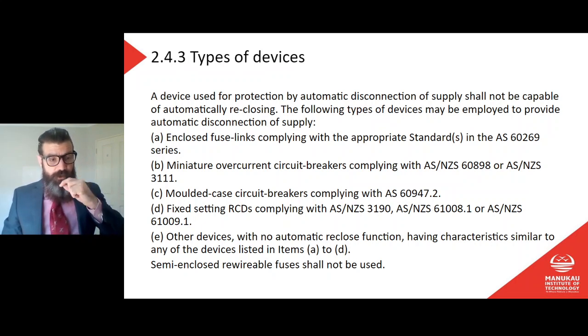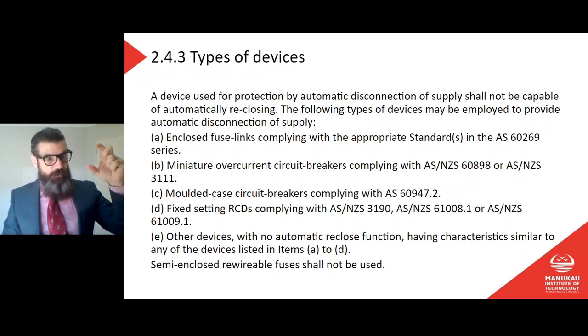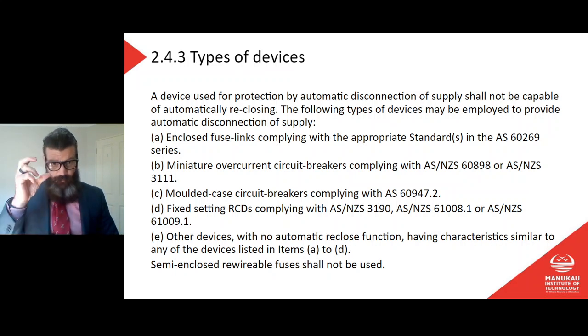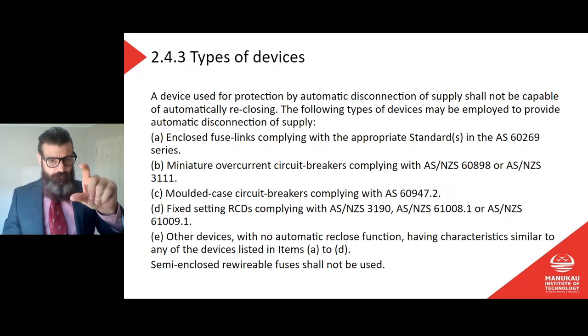Plug-in circuit breaker. So this is something that will, in the rewirable fuse base, you just take out the fuse holder, throw it away, you get a plug-in circuit breaker and you plug it into the fuse base, and it acts like any other normal fuse circuit breaker. It's a great option to replace a rewirable because it doesn't require you to replace the base at all. It doesn't require you to disconnect any wiring or anything like that. Just pull out the rewirable, put the new one in.